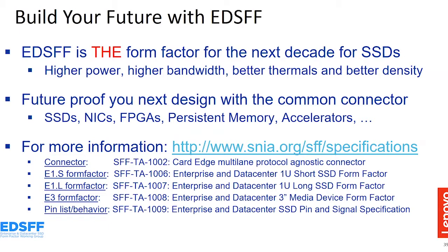Okay, so basically EDSFF is this new form factor for SSDs. It's higher power, higher bandwidth. The EDSFF connector supports well over 40 watts. I think it's maybe 70 plus. So higher power E1.S, E1.L, they all support higher power. It's really just a question of thermal, but you get better thermals with this connector and this form factor.